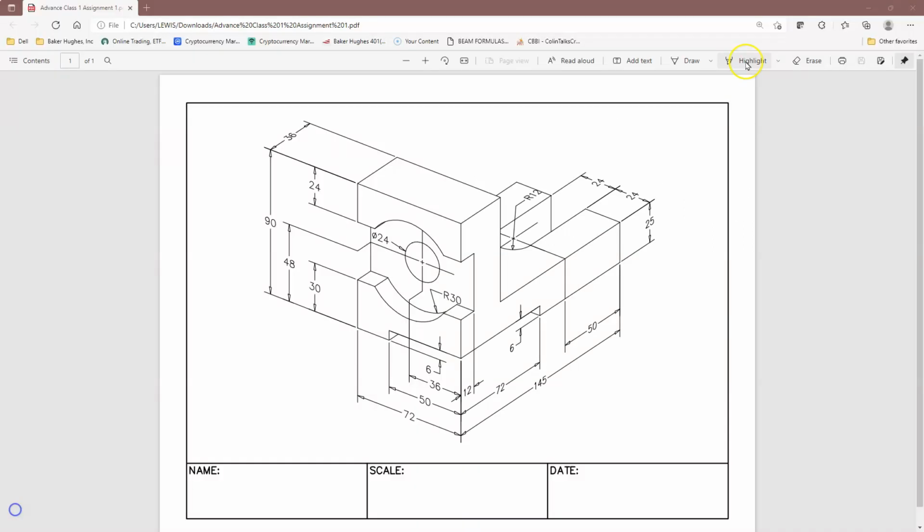And I'm using the term subtract, which is coming from AutoCAD, but in Inventor it is nothing more than an extrusion. So here in the drawing, you can see that I should have all the dimensions that I'm going to need, and I'm going to start off creating an L shape. The dimensions I'm going to need are the 72 and the 145, so I have the length and the width, and then here's the height, which is 90. And I'm also going to need this 36 and that 25.